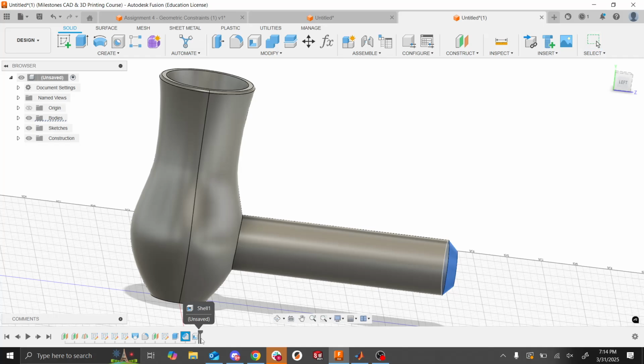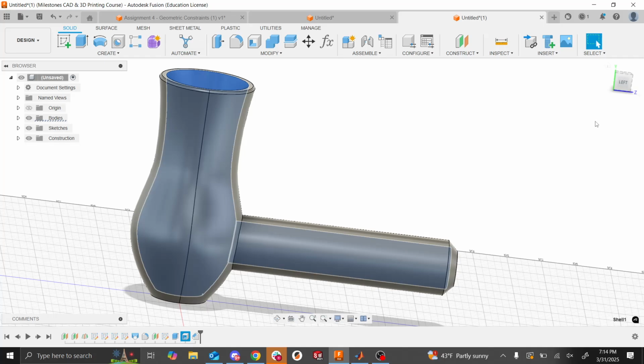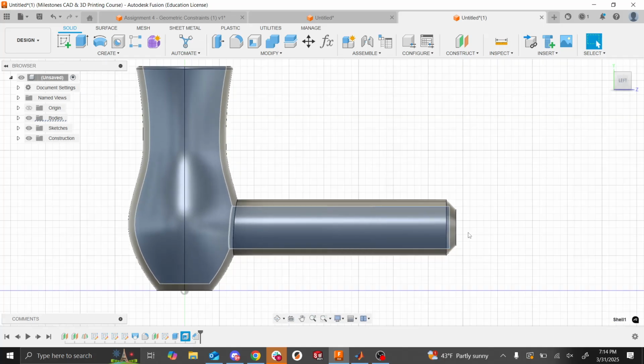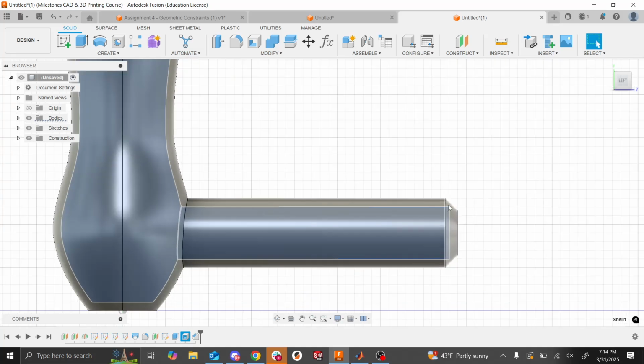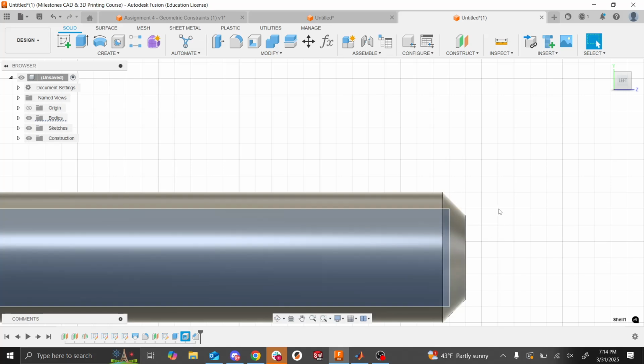If we changed the order at which we did some of these operations, you might get a different geometry. So in this case, if you add the chamfer after the shell, you can see this feature here or this area is kind of thin. But if we changed it so the shell is after, you see it's nice and smooth, or it's nice and constant width, right?